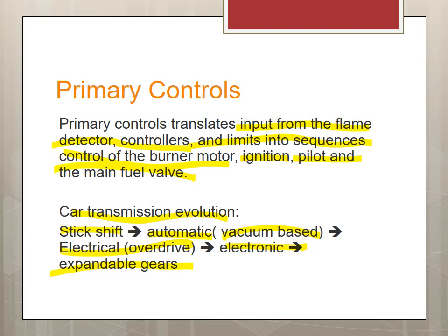If I have to follow up with the primary controls, they start with mechanical timers, mechanical relays, that went on to semiconductors, that went on with the single screen main controls, and also semiconductors, and now we have a whole processor, computer processor, that will control the boiler with a touch screen. So that's like the recent thing in primary controls.